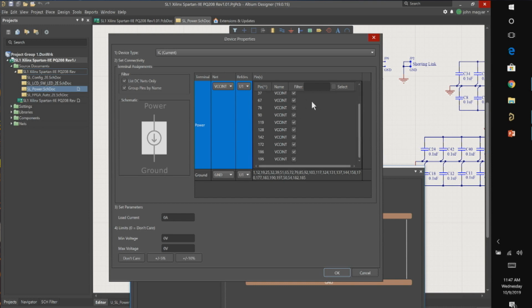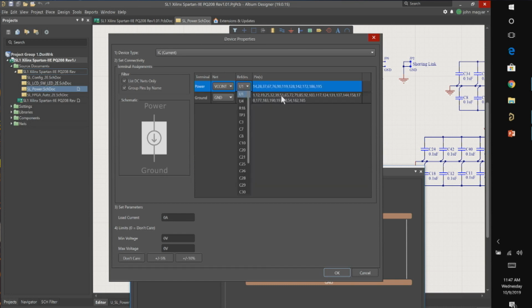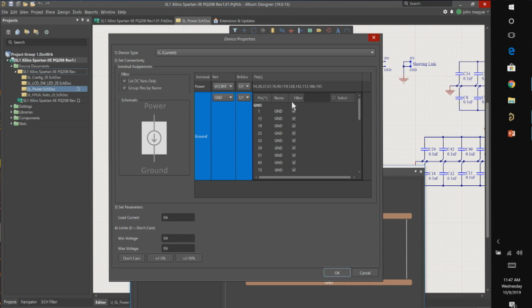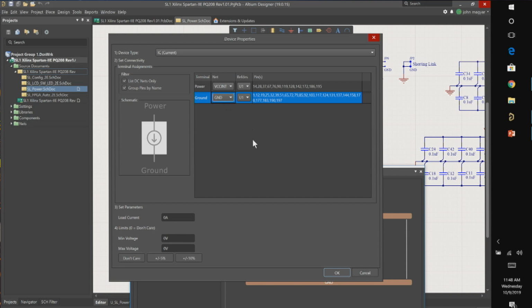And to show you something interesting, I can look at every connection and choose whether I want to include that in the analysis. So all the power connections now for ground, what happens sometimes is things connected to ground aren't really in the power circuit. They may be logically tied to ground. So I have the option to uncheck things that are logical connections to ground or power, and then include that. So that's a nice, accurate way of defining what the load is.